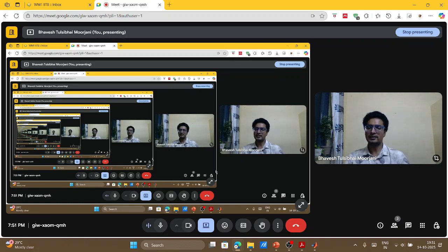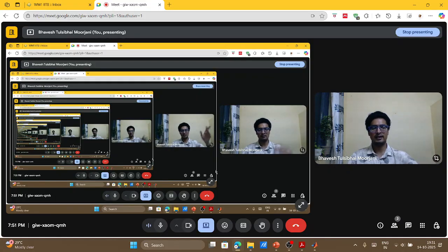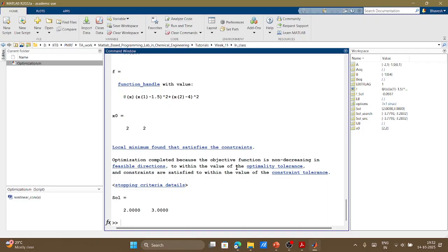Now you can do that sensitivity analysis based on your own also. Let's say we change the value of temperature for feed input and see how the conversion varies, or how the outlet temperature varies in the PFR reactor, right? So that is a kind of sensitivity analysis, out of which, if you have to find the optimum value, you put some condition and find the optimum value, or you create your entire output concentration as a function and put it into this optimizer, right? So that can also be done. So it's up to you the way you want to choose the optimization process, right?